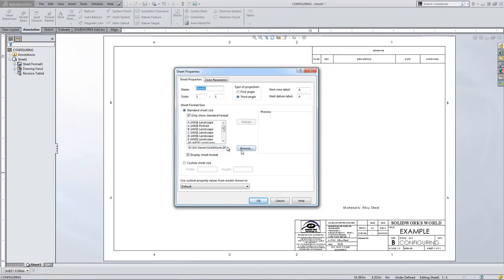And it decides to use some out-of-the-box SOLIDWORKS one instead, which looks horrible compared to what you did. So you have to resave the sheet properties or in the template? First we're saving the sheet format out, so we have the individual title block with the lines and the notes in the image by itself so that we can bring it into other drawings if we're changing paper size.